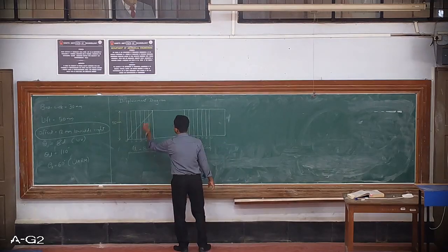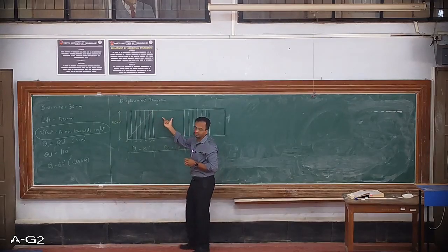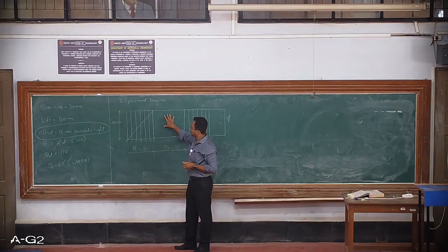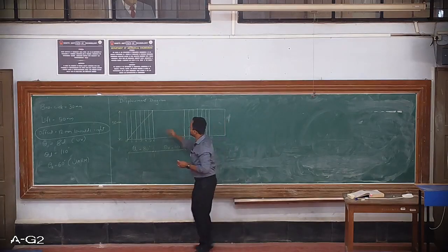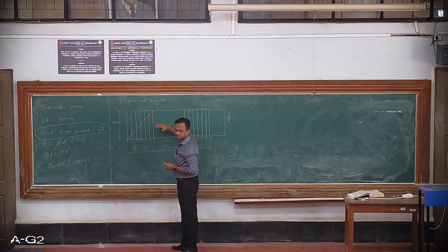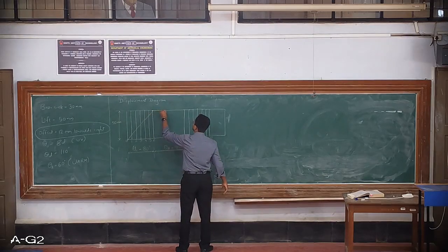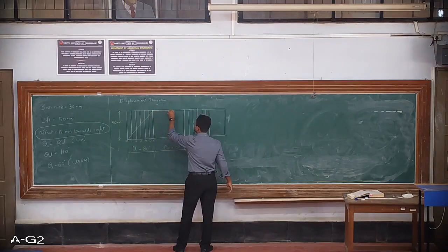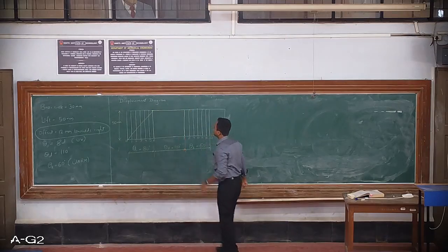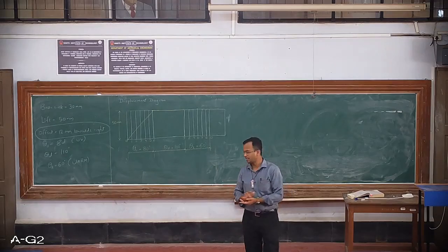So once it reaches here, it is followed by a dwell period. So in dwell period, we know that the radius is not changing of the cam profile, and also the follower displacement will be 0. That means it will neither rise nor it will return or fall back. It will be horizontal. So the displacement of the follower in the dwell portion will always be horizontal. Okay. I hope it is clear till this step.